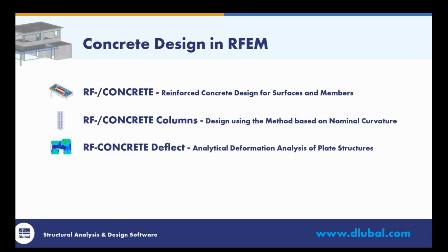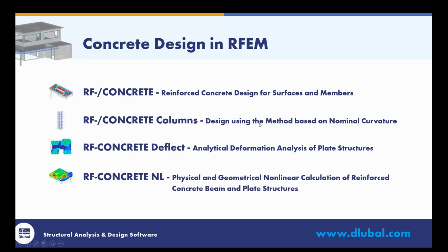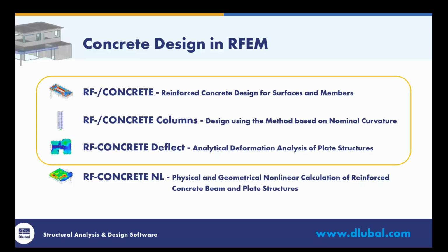Then we have the module RF-CONCRETE Deflect, which is actually an add-on for RF-CONCRETE Surfaces. The next thing would be RF-CONCRETE NL for nonlinear, which can do a physically and geometrically nonlinear calculation of reinforced concrete beams and plate structures. For RStab, this is already included in the concrete module. And later on, I will show you designs in the marked modules.